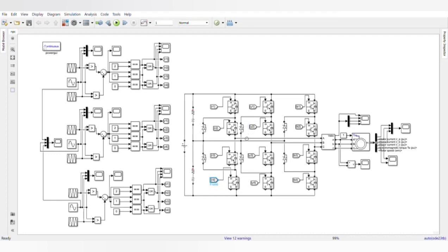In this main circuit, we require 12 IGBTs, which are used as the switching devices in the inverter, and 6 diodes. The application that is simulated with the new neutral point clamp PWM inverter is an induction motor, which is a squirrel cage induction motor.